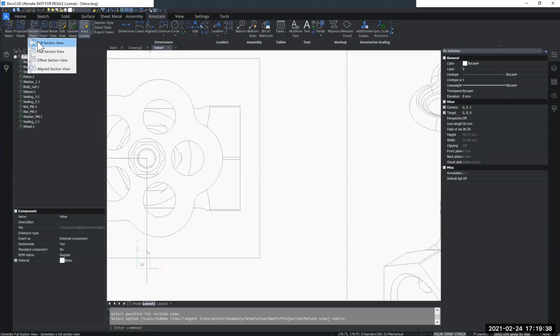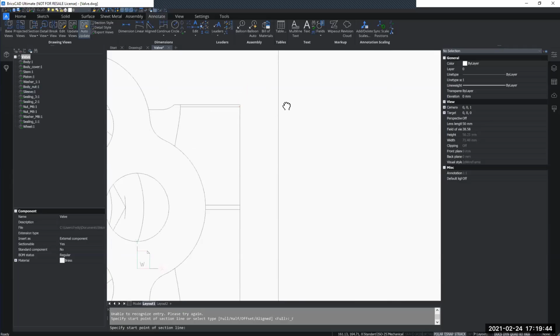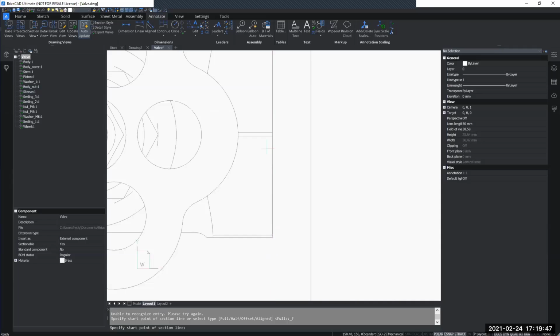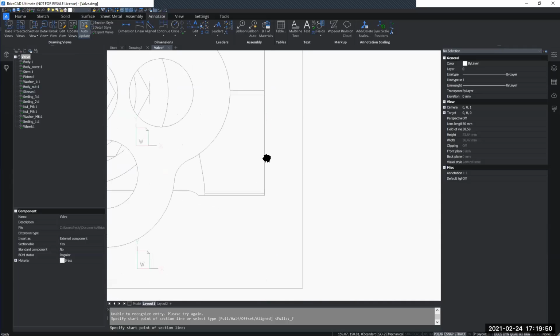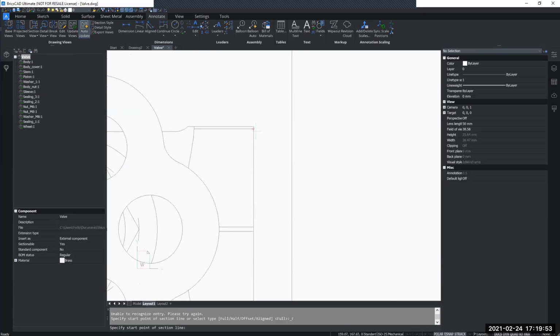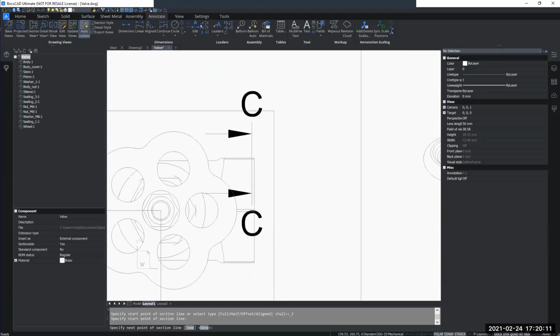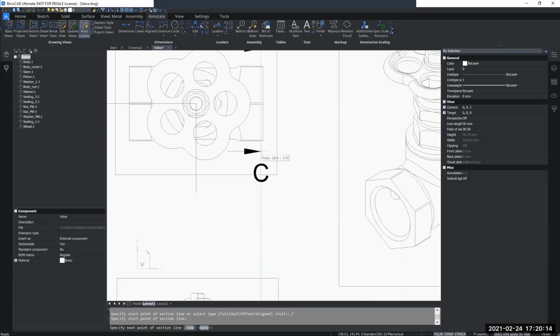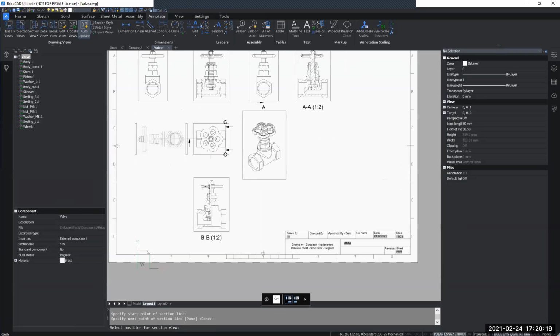So then I can go ahead and create another full section view, select the drawing view. Now I just want to capture the silhouette of this face here, basically. So I will just start my section line a little bit in past the face of it. Specifically, it doesn't matter as long as it doesn't touch much else or go past this shape, just a few millimeters past. I will start my line, draw it downwards the same way as before. And I will move it to the side.